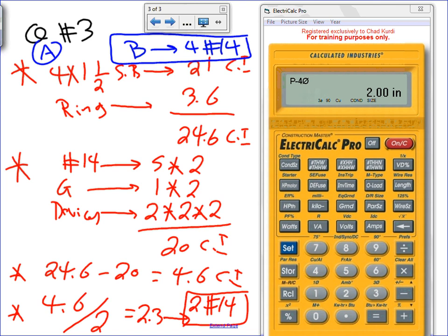I don't know how you do the devices. I have 2 of them, right? Is it a 2 duplex receptacle that makes it 2? A 2 duplex receptacle counts as 2 devices. A duplex is 2 receptacles in 1 yoke. A 2 duplex is actually 2 devices. If you treated it as a quad, even as a quad, it's going to count as 2 because they're 2 big yokes, I guess. Okay, any questions about this? We can't use it in the calculator.